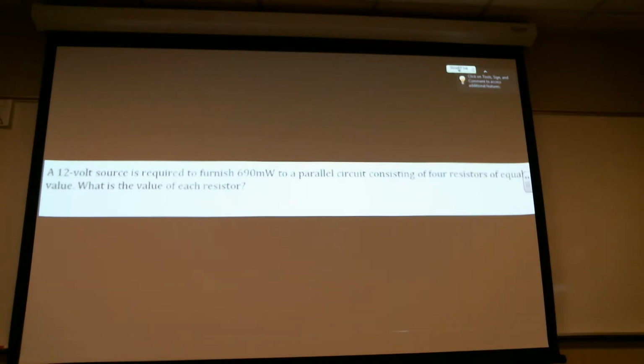Now you can do that, and here's your other option. You take your volts and your power, you divide power by volts, and you've got current. So now you come over here and you've got current and you've got volts. And volts divided by current, you've got resistance. Oh, so you just do it that way anyways. So you can do it this way.